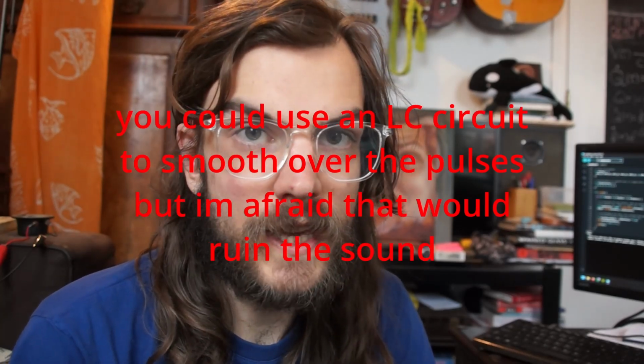So the question becomes, how does it make this sound? If we want a good guitar effect, we're going to need an analog sound, meaning that we can have different voltage levels, but this pin that this Arduino is connected to can only do on or off, so 5 volts or 0 volts in this case. The Arduino does have pulse width modulation, which you can control using the analog write command, but that doesn't change the voltage, it only changes the duty cycle, which means it's not fit to make sound with.